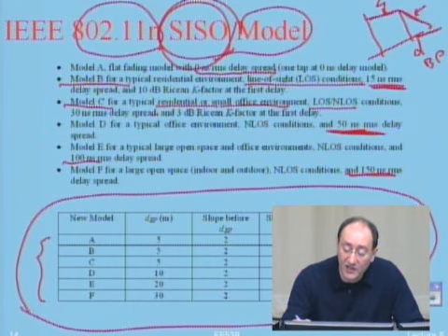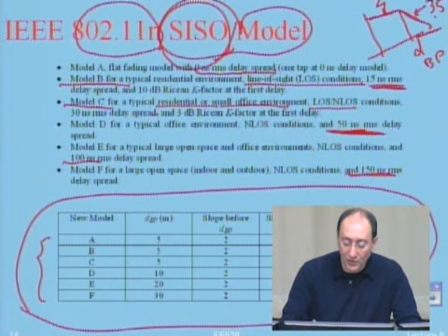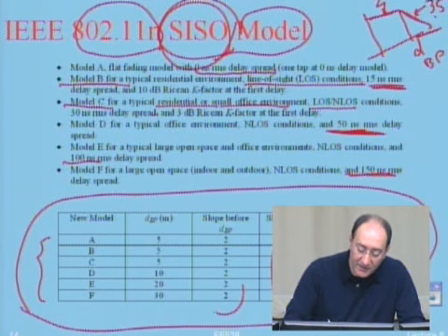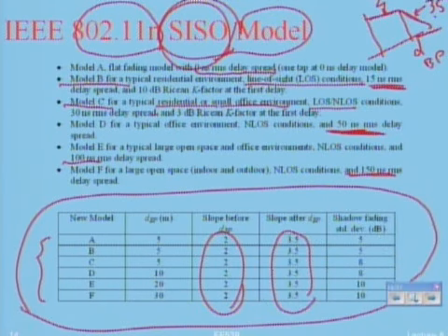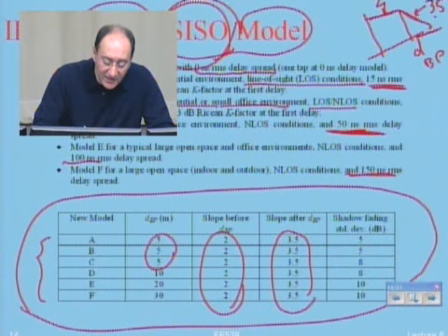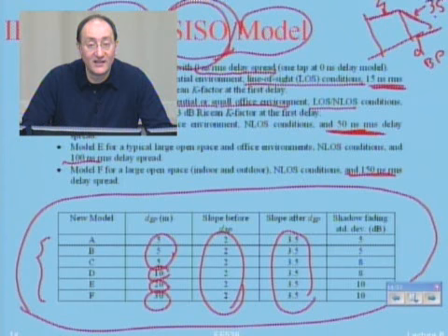The slope at the beginning is 2, and here it is 3.5 for all of them. Look at that. But what they changed is this break point. The break point for the first 4, for example, is 5 meters, then 10, 20, and 30. Those are the path loss models that they have.